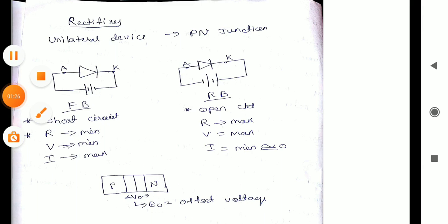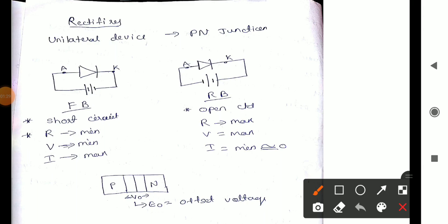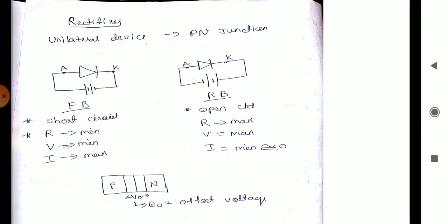In general, we are dealing with semiconductor devices, and these semiconductor devices are like switches. When they are conducting, for example in forward bias, we studied the VI characteristics: as voltage increases, the current also increases in an exponential way. In reverse bias, the current is very small. In the ideal case, we consider reverse bias as an open circuit or an off state.